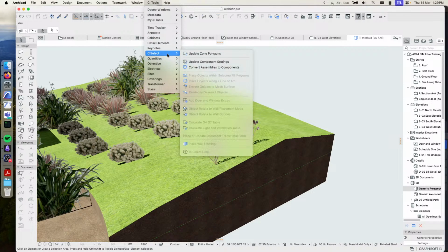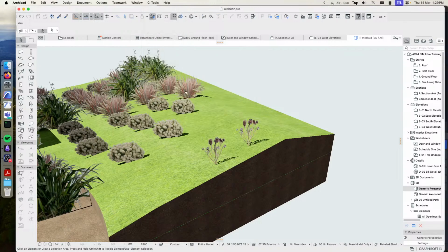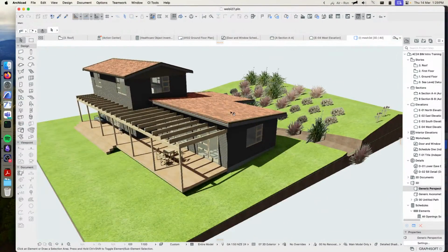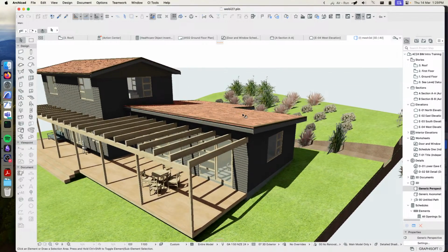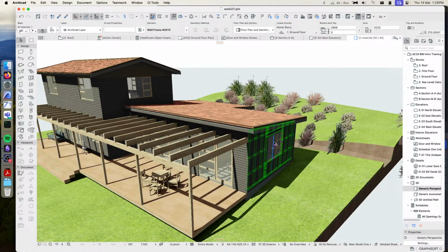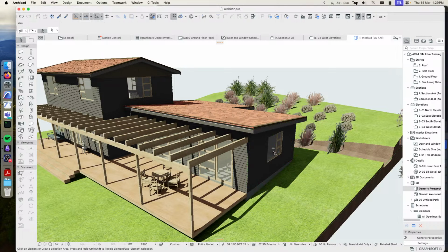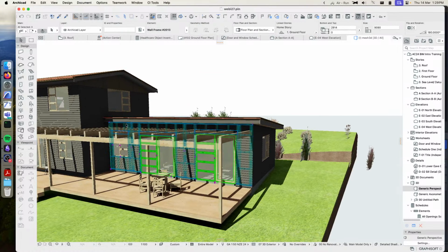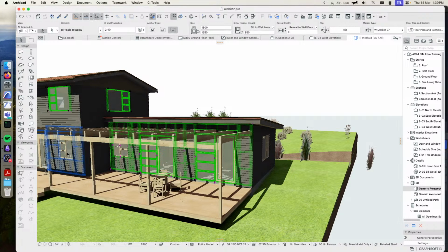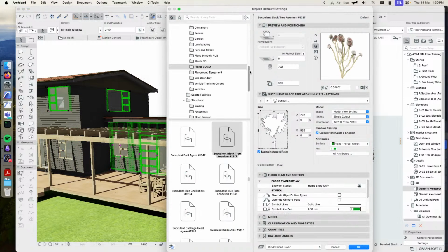Alright, the last thing that I wanted to show today was the window and door extras function. So we'll just quickly jump across to that. What this one does is it is intended to let you essentially put curtains or blinds or something onto windows and doors. It also will work with the lintel objects, so if you want to just go around and place lintels, you can do that as well. So we can select, it's a wall frame. Select a bunch of windows and doors. Okay, and we'll go CI select, add window and door extras.